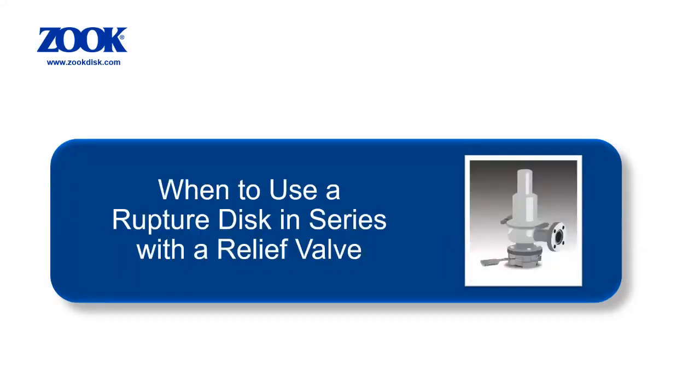This is a very common application where a rupture disc is used to isolate and protect the valve from the process media. The inexpensive rupture disc is the only part exposed to the process until an actual overpressure condition occurs. This is extremely advantageous in highly corrosive applications, combining the advantages of a fast-acting leak-tight rupture disc below and the reclosing functionality of the valve above. Also, depending on the disc model, the valve can be tested in situ without the need of removal, thus saving significant downtime and costs.